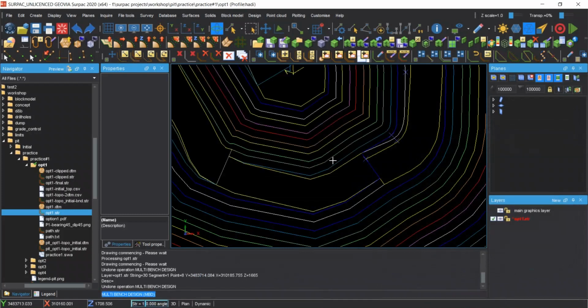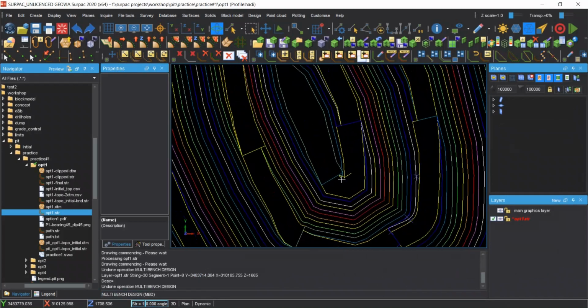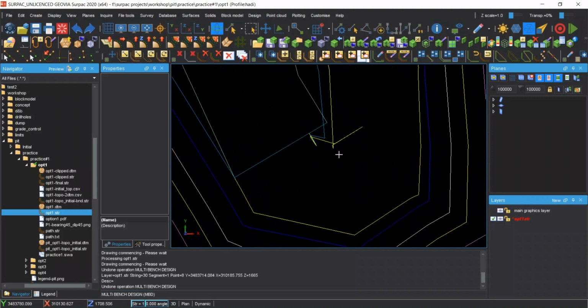Now that everything looks okay here in this bench, let's deal with the other issue here, that the points are irrational. Well, if you're familiar with Surpac, it calls these crossing points and segments crossovers or spikes. Not only will the DTM creation be wrong and invalid, the construction of the ramp and benches is not possible and cannot be applicable in the real world.